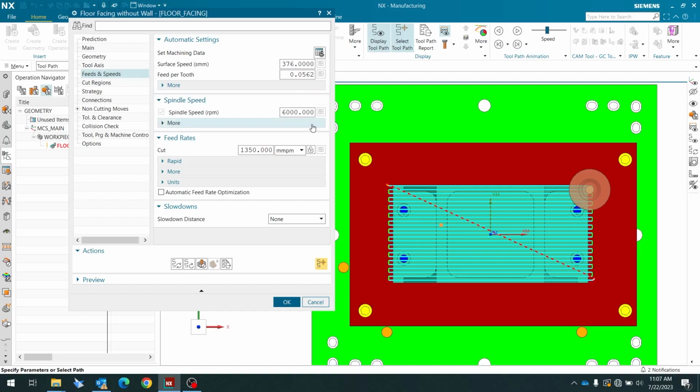Someone might have observed on the insert box, insert meaning the cutter inserts, they mention the maximum RPM you can give for that particular insert and whether the maximum feed you have given is okay or not for that cutter. You may cross check.